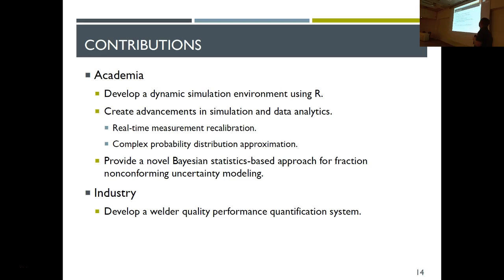So, contributions. From the academia side, this research developed a dynamic simulation environment using R, and this research also created advancements in simulation and data analytics. First one is real-time measurements recalibration. The second one is complex probability distribution approximation using the MCMC method. And this research also provided a novel Bayesian statistics-based approach for fraction non-conforming uncertainty modeling. And from the industry side, we developed a welder quality performance quantification system to improve their quality-related decision-making processes.